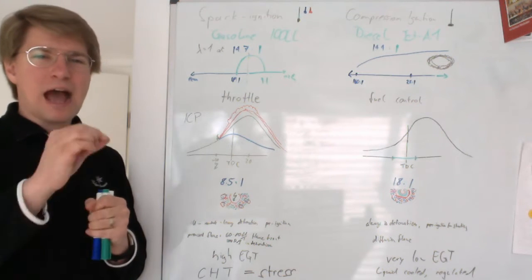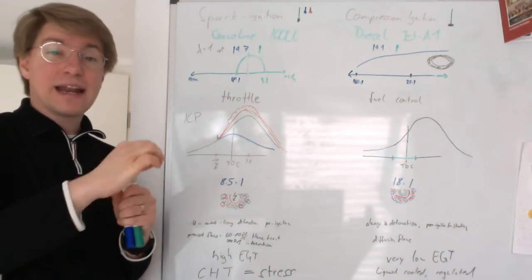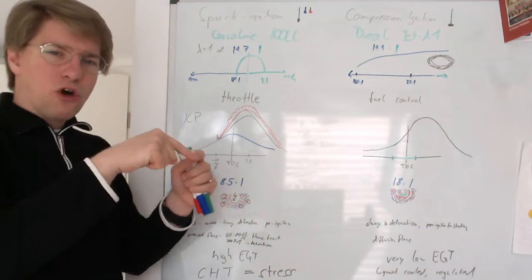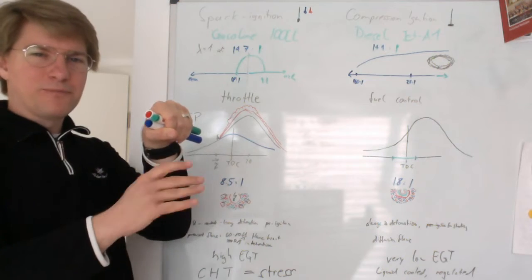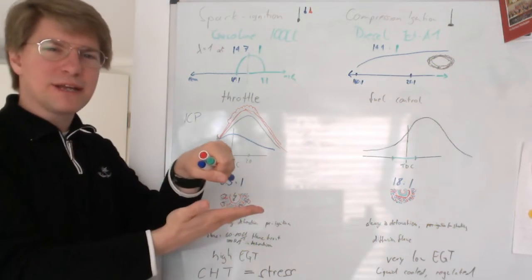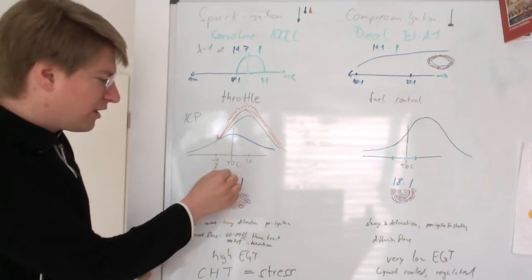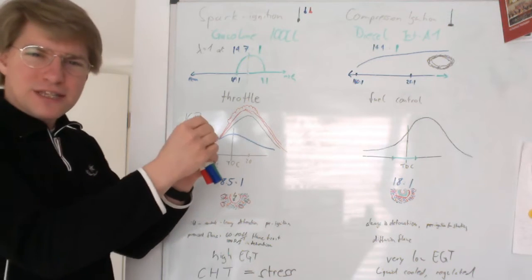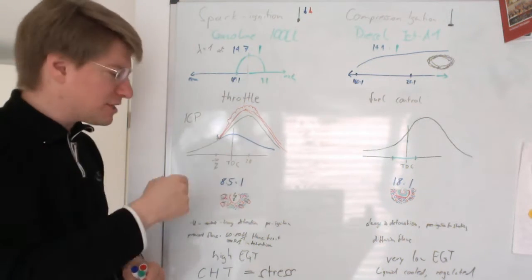And what then happens is you have a glowing hot spot in the cylinder, and at some point this glowing hot spot is so powerful, combined with the high compression of the fuel air mixture, that it ignites before even the spark plug fires. So the flame front, the primary flame front, gets going from this hot glow plug, I call it, before the spark even fires.